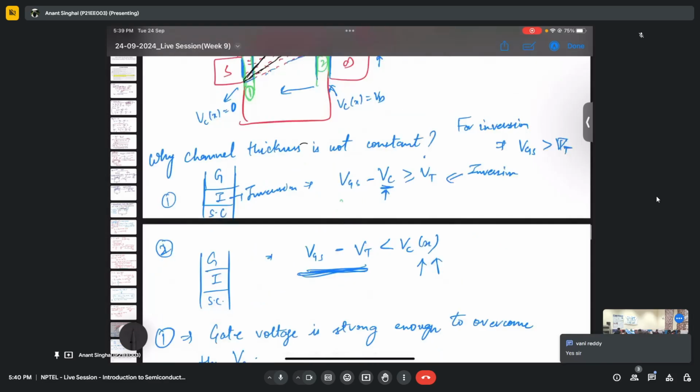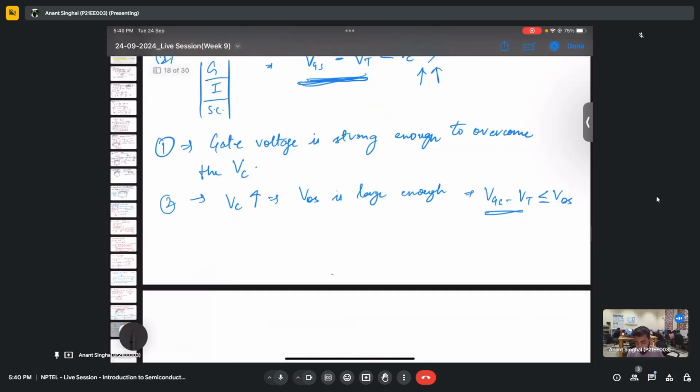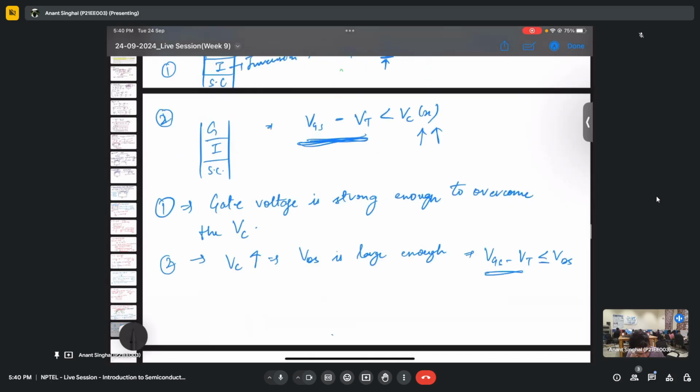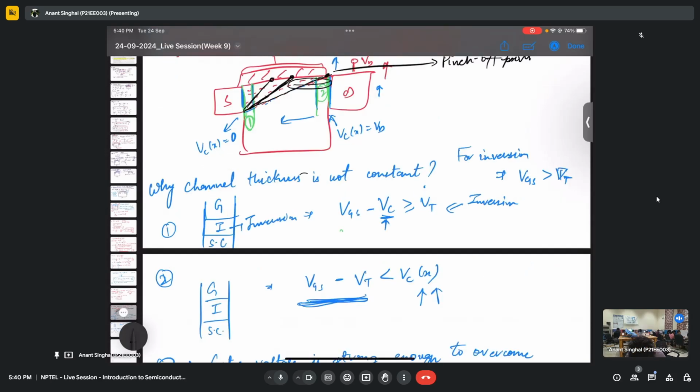Okay, that is good. So if it makes sense, then what do we have? We have the tapered off channel, and the moment this VGS minus VT is getting greater than that of VDS, the channel is getting tapered off and there are no electrons in the channel, as you can see. In this diagram, there are no electrons here if the channel is like this. That is what is known as a pinch off point, and for this VDS is greater than VGS minus VT. Now if we assume that the transistor is working in linear mode of operation, give me a moment.